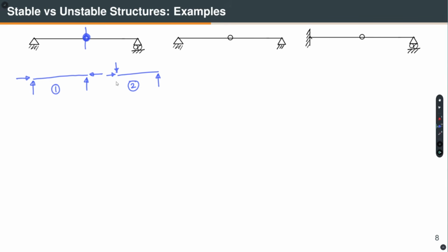So, for each, how many equations of equilibrium we have? So, n is equal to 2, okay, and r is equal to how much? We have 2 unknowns here, 2 unknowns there and 1 here. So, 2 plus 2 is 4, plus 1 is 5. Okay. So, how many equations of equilibrium? 3n is equal to 6 and this is greater than r, which is equal to 5.